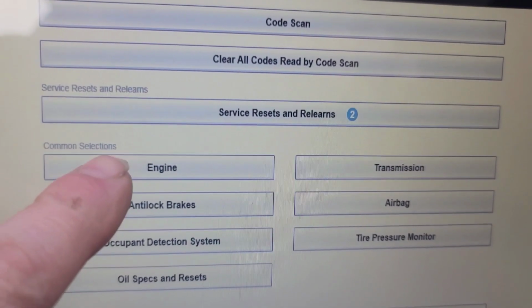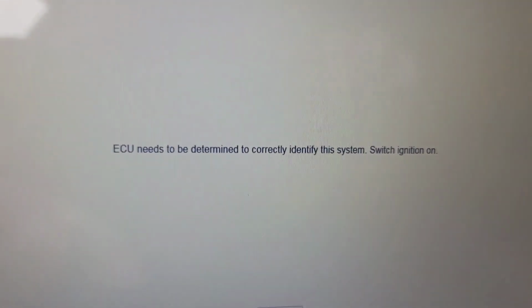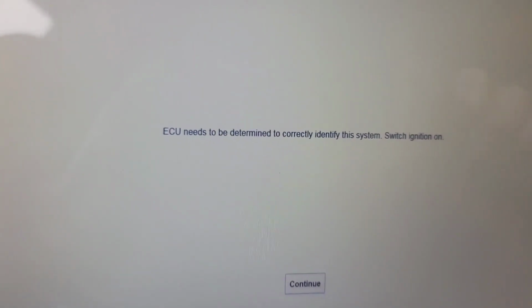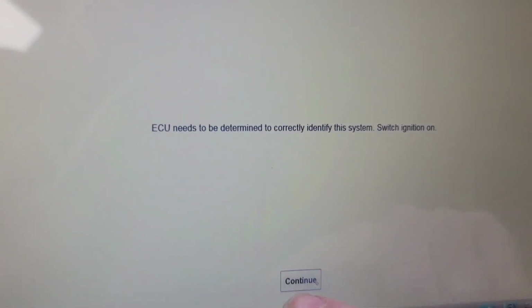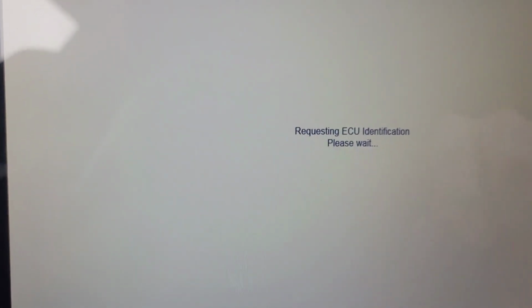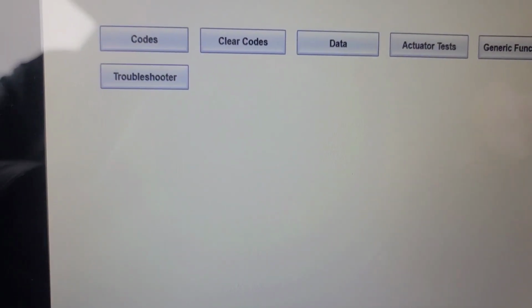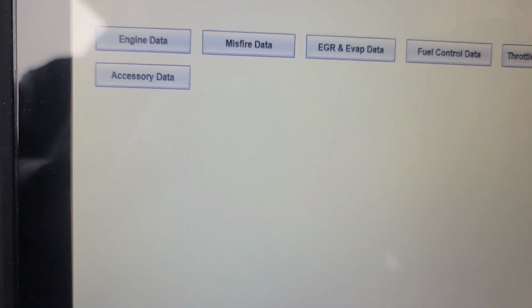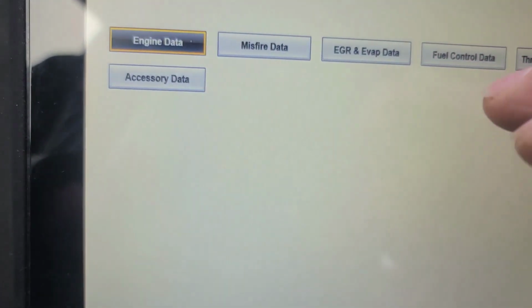So we're back working on this Subaru Forester this morning. Going to rescan it. It isn't that cold today. It's only like -5 or -6. And I'm wondering if the intake air temp sensor is part of the math. And of course, by the time I get the key on and read the temperature, the MAF sensor may warm up and make the intake air temperature sensor reading a little higher than real.